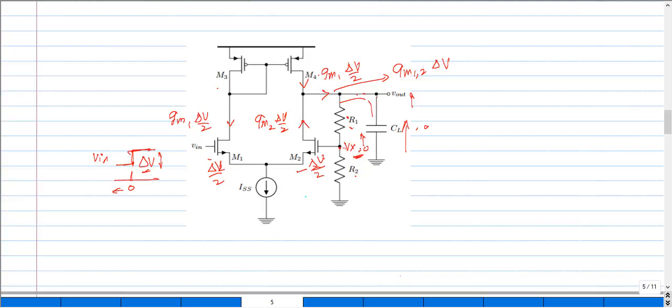So if the circuit follows this kind of current action, then obviously we would end up with a Vout with respect to time that could be written as something like V0, and then the gain, that is nothing but our closed loop gain, times e to the power of minus t by tau CL, correct? Yeah, so basically the output would follow this kind of expression, which means that the circuit still has that linear system property in it. Now let us go for a different case.